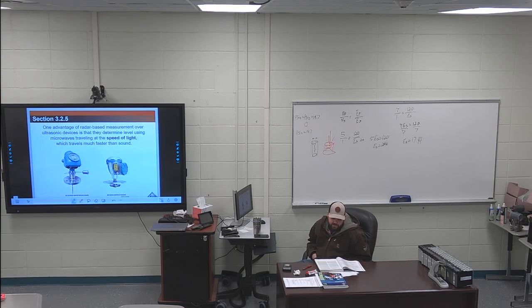340, pressure-based level measuring devices. 341, hydrostatic head devices. I highlighted the heading of that, 341, along with the first sentence. Level can be accurately measured by determining the hydrostatic head pressure produced by a fluid and converting the pressure measurement to a height or depth.